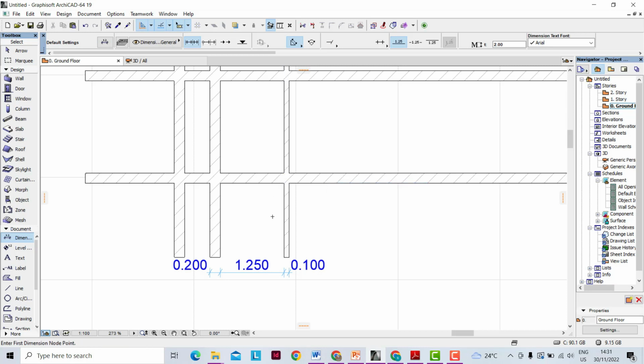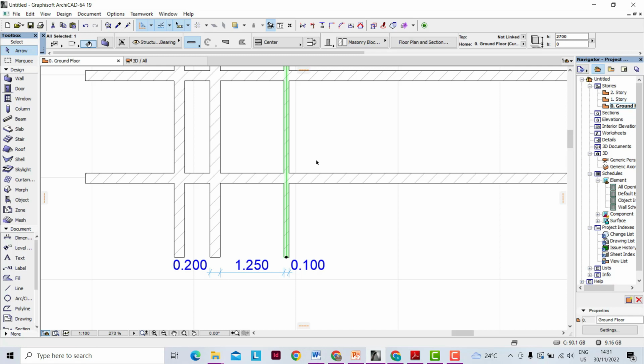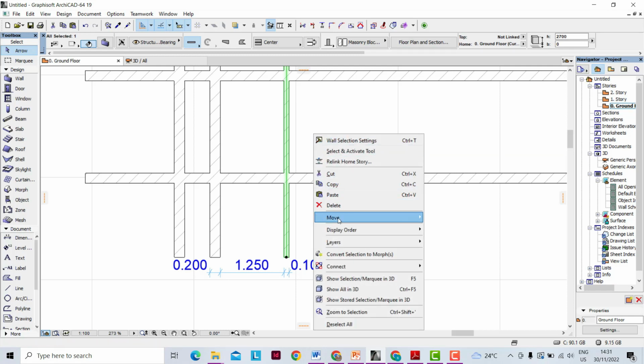But for us to disengage the cursor, we will click on the arrow, and our cursor will be free, so that we can now select this wall, and then we enter the command for dragging. Again, we said move.